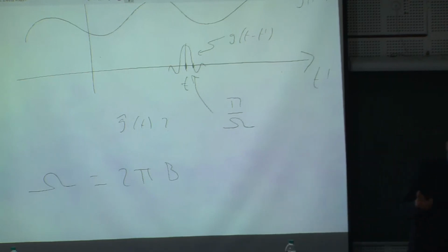I have a ratio between the main lobe and the first side lobe of 13.6 dB. I think it was 13.6. And now, so you read once in a book, use triangular window, or raised cosine window, Hamming window, or Hanning window.